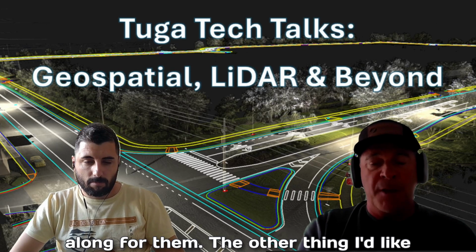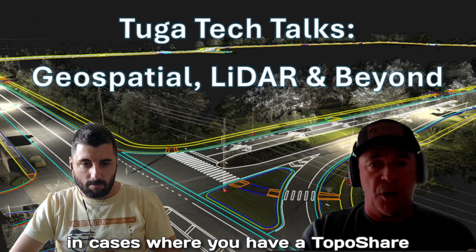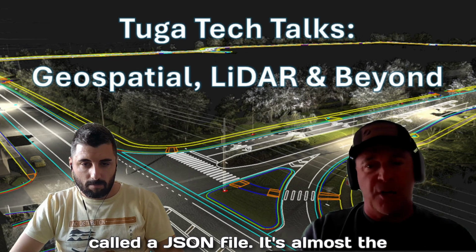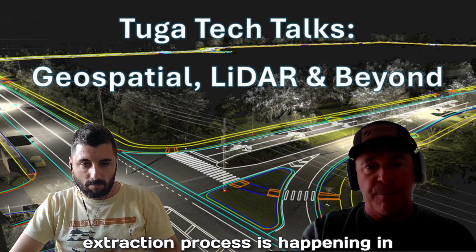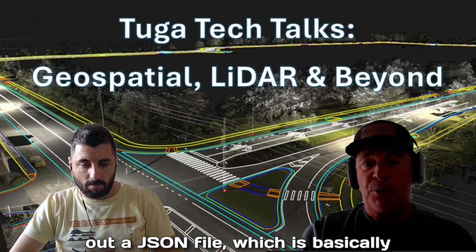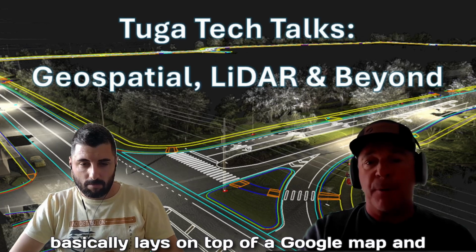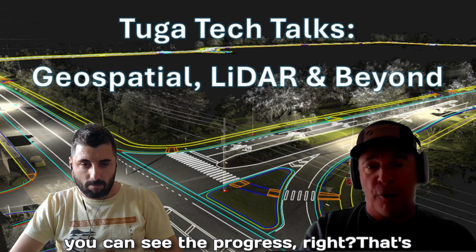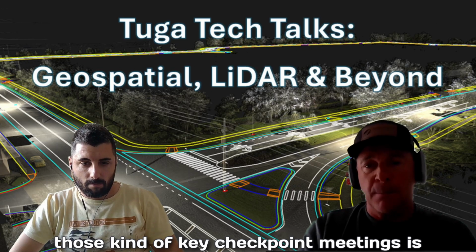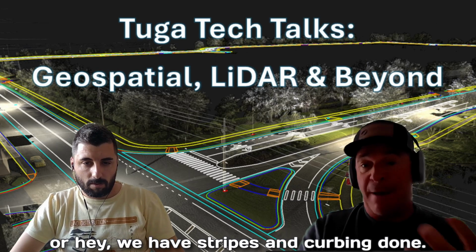The other thing I'd like to do, if we had the ability to do it, in cases where you have a TopoShare environment that your geospatial team's working with, you can use what they call a JSON file. The extraction process is happening in MicroStation and Topodot. We're saving out a JSON file, which is basically a web viewable vector file. And it basically lays on top of a Google Map, and you can see the progress, right? That's another very effective way, especially in those key checkpoint meetings, is let's take a look at the progress. You can see, hey, we just have stripes done, or hey, we have stripes and curbing done.